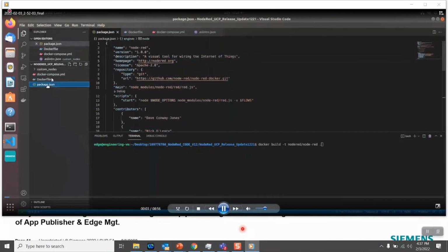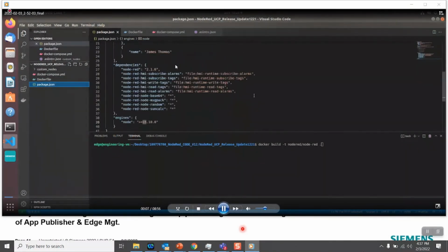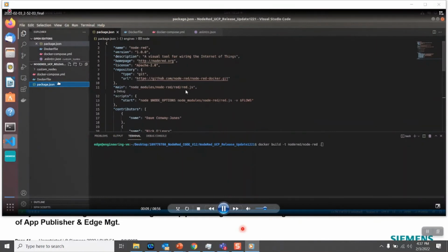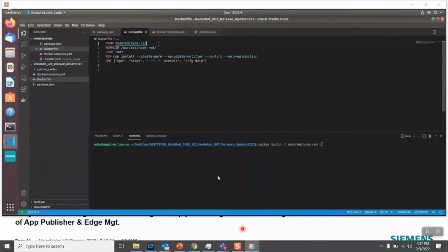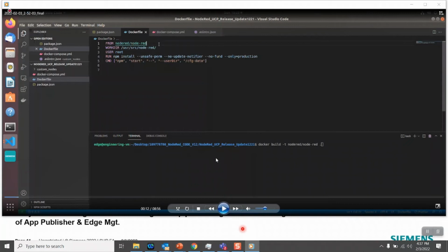We have Dockerized this application. This is the required code, which has all the dependencies to run Node-RED. This application is nothing but a dashboard we have created in Node-RED. In Node-RED we have used the Modbus protocol, which communicates with the S7 1500 PLC. Over here we are going to create a Dockerized image of the Node-RED application.